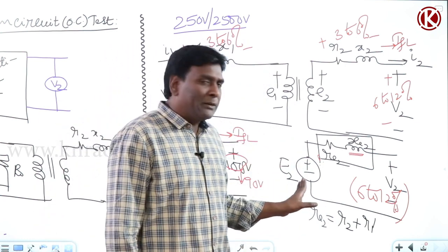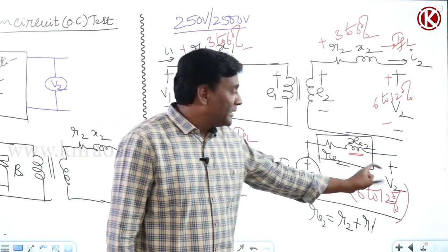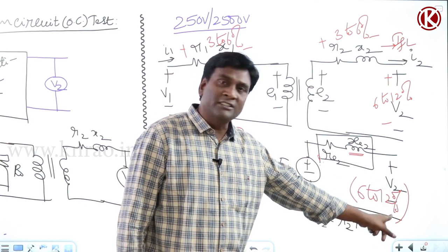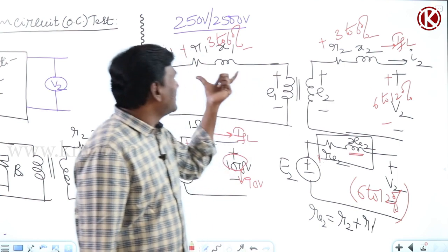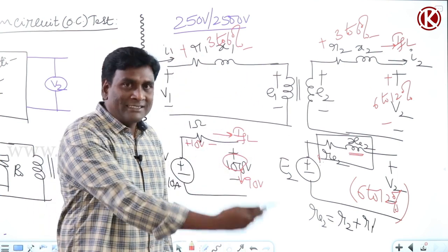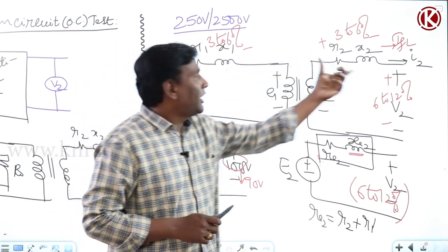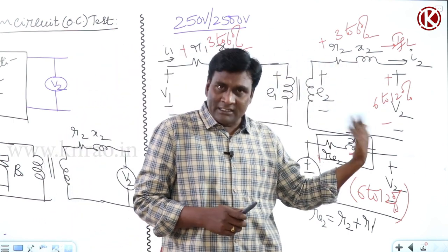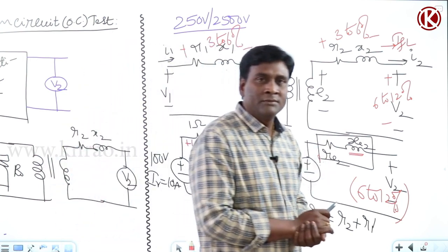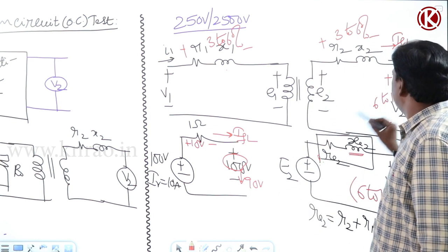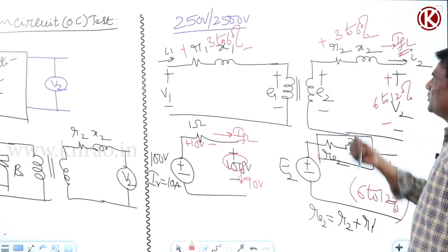Anyway, let me start again. The moment this is least, voltage drop is going to be least, and terminal voltage variation will be least. That variation is 6 to 12%, so 6 to 12% here means 3 to 6% here. In the next session of the SC test, I am going to tell you Z1 equal to Z2 dash or Z2 equal to Z1 dash, immediately after this. Now forget about it. Now if you inject full load current, how much is the voltage drop here?